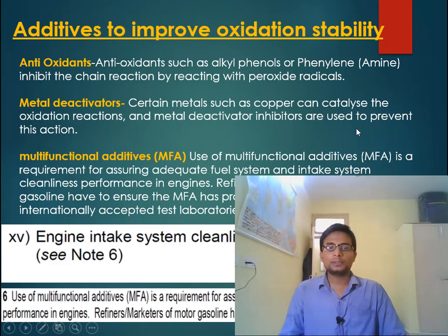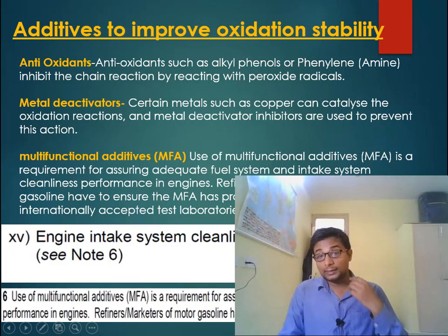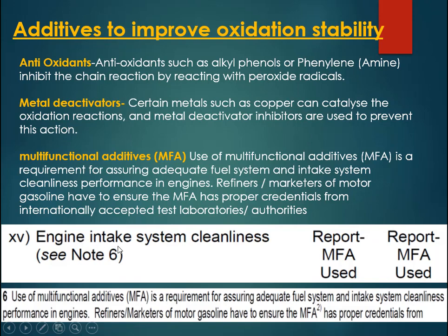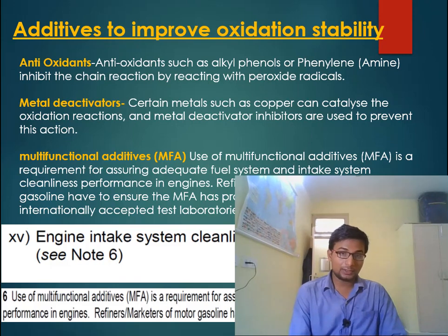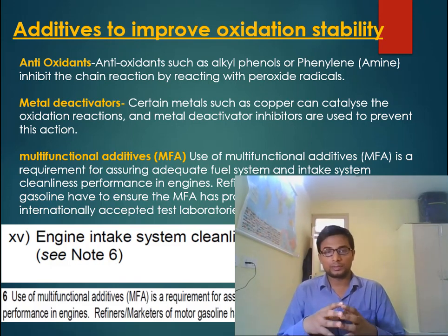Okay. Apart from that, in petrol we add multifunctional additives basically to ensure the proper cleaning of the fuel system and intake system of any engine. And there is another limitation on the BS4 quality parameter of petrol, that is engine intake system cleanness. Basically you have to report whether you have used multifunctional additives or not, and that multifunctional additive should have a credential from a testing agency, that it is a certified multifunctional additive. Okay. IOCL, which sells superior gasoline, extra premium gasoline, contains a very good amount of multifunctional additives which ensure the cleanliness of the intake system. Okay.